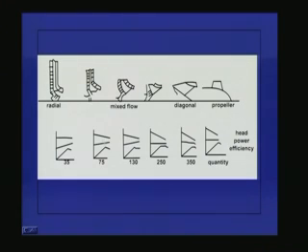Here in these figures there are three curves. On the x axis we actually plot the discharge, and on the y axis we plot the head, power and efficiency. So, this curve is the head versus discharge curve for a typical pump which has a specific speed of 35, this is the power versus discharge curve, and this one is the efficiency versus discharge curve, and these curves can be plotted for any type of impeller or for any pump.